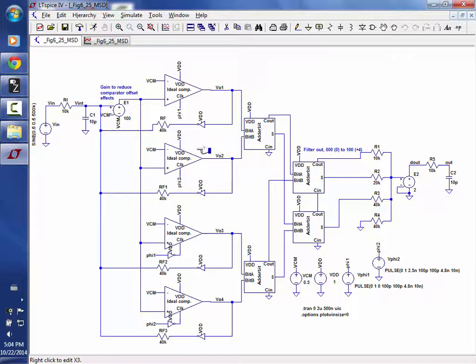Now, one thing that you'll do in your projects, and we'll talk more about this later, is, you see how this signal goes high and it stays high? How long would Vout1 stay high or low? Let's double click to give you an answer. Knowing the clock, it's clocked with phi1. It stays the whole 10 nanoseconds. It doesn't change until the following rising edge of that 10 nanosecond clock. Now this one, same thing, except it's delayed by 2.5, but they all only change every 10 nanoseconds.